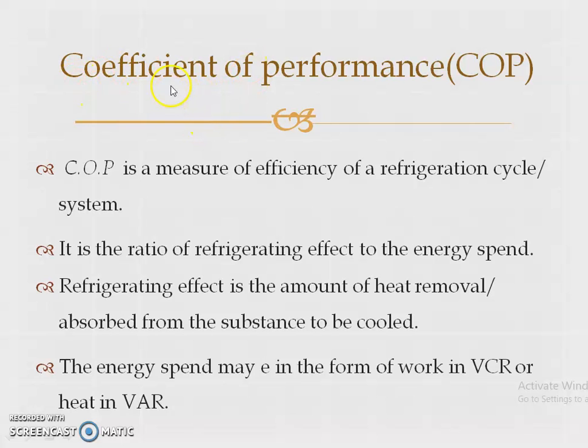The COP value is denoted for the refrigeration and air conditioning system. That is the coefficient of performance. The coefficient of performance is a measure of efficiency of a refrigeration cycle and also of the system. It is the ratio of refrigerating effect to the energy spent. The refrigerating effect is the amount of heat removed and absorbed from the substance to be cooled.